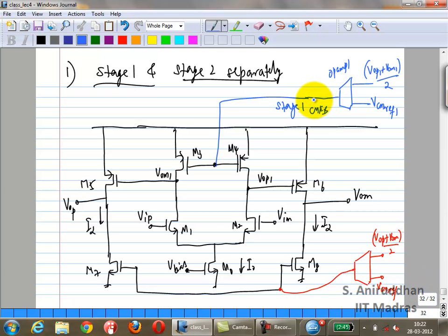So the transconductor also has its own output impedance. What is the gain of that single stage op amp? In this case that op amp happens to be a single stage op amp. That's what we did for the first stage. What is the gain of the single stage op amp? It's GM1 times, if we just look at this one, GM of the NMOS times GDS of the NMOS over GDS of NMOS plus GDS of PMOS. That is the gain. So it is actually driving a voltage.